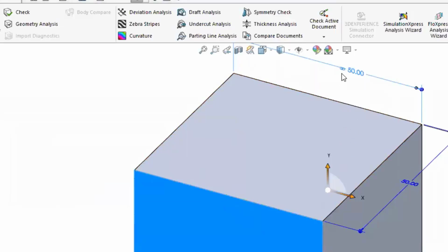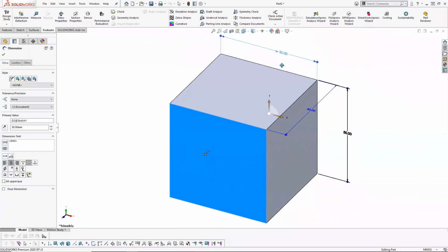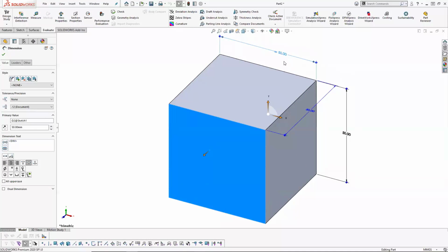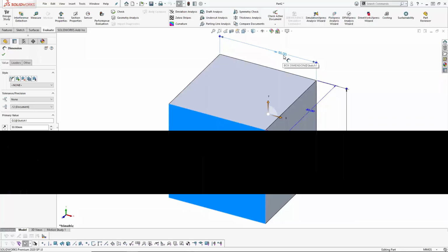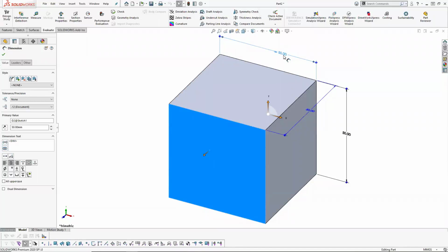And then it's going to put the little infinity symbol here. That basically creates a variable called box width dimension and assigns this dimension to that variable. But the key thing here is it's creating it through what's called a link. So while I like link values, I'm more in favor of actually creating variables and then assigning those variables. But if you are using link values, you can right click on a single dimension.